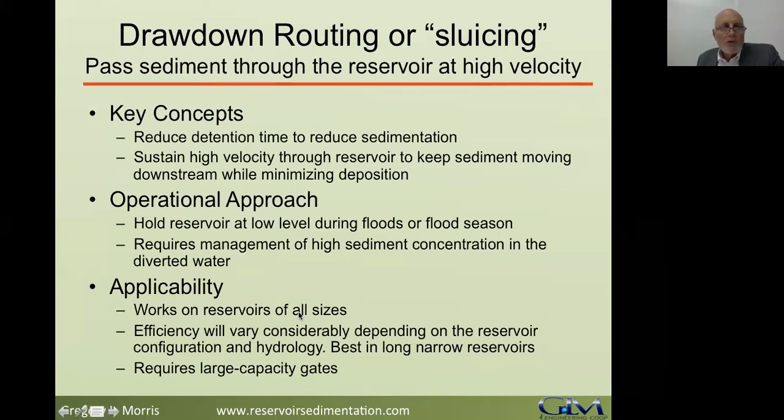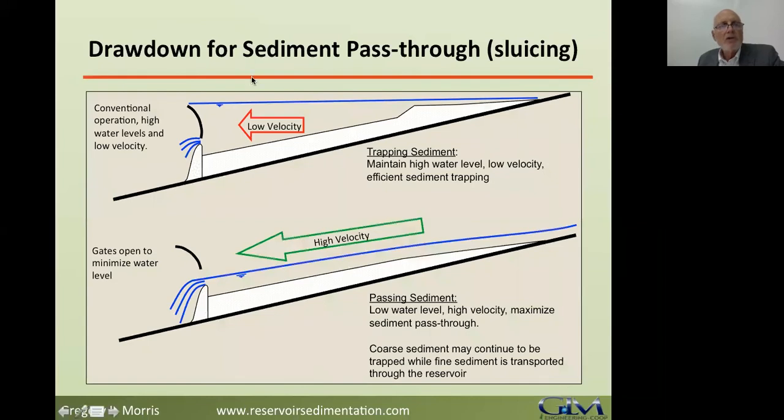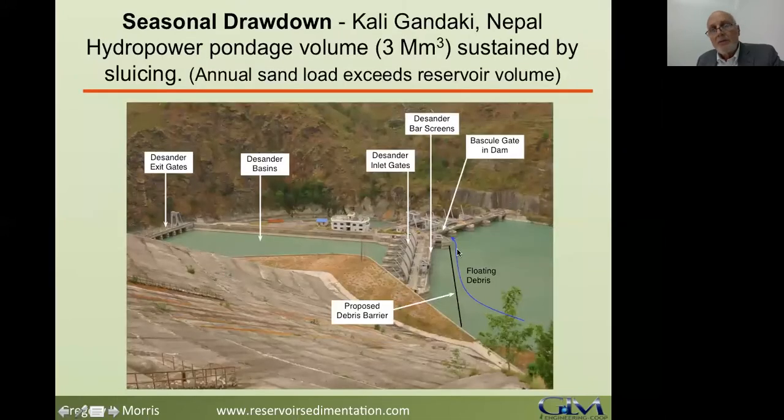Applicability, it'll work on reservoirs of all sizes. The efficiency varies considerably depending on the reservoir, the geometry, or hydrology, but it does require large capacity gates because you have to pass flood flows through the reservoir. This graphic shows you conceptually passing a flood, maintaining the reservoir at a high level versus passing the same flood at a high velocity with a reservoir at a low level. In the top graph, you'll see you're going to be trapping sediment, and the bottom one, you'll be passing sediment through the reservoir.